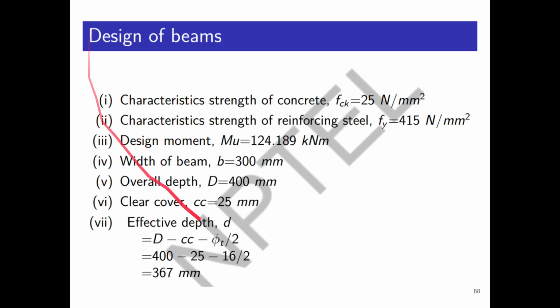Now we will be actually designing based on the moment we have generated. Definitely that value will be similar. That was, I think, 300 by 500, this is close to 300 by 400. But if we give 300 by 500, that is uneconomical. If it is satisfying here only, why give that value? We are not only casting one beam, we will be casting hundreds of beams because it will be a G plus 3. Therefore it will be a huge uneconomical section if we give unnecessary dimensions.